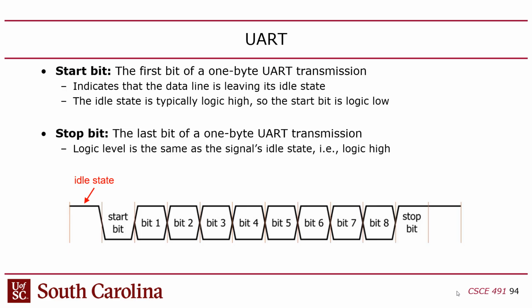It's the reciprocal of the baud rate. So you agree on a baud rate, and the inverse of the baud rate is a bit time, and that's how long you have to hold that low for a start. How does the receiver know you're starting? Well, because it's always looking for a low. When it goes low, that means it's starting.